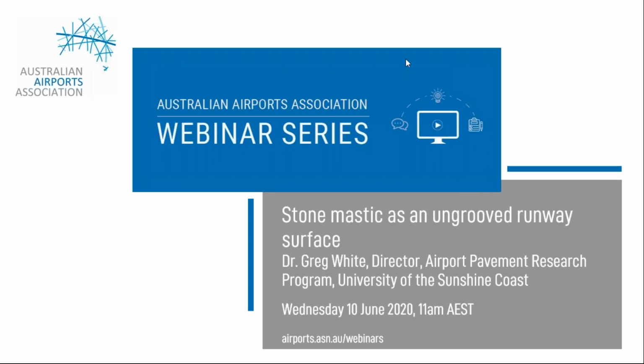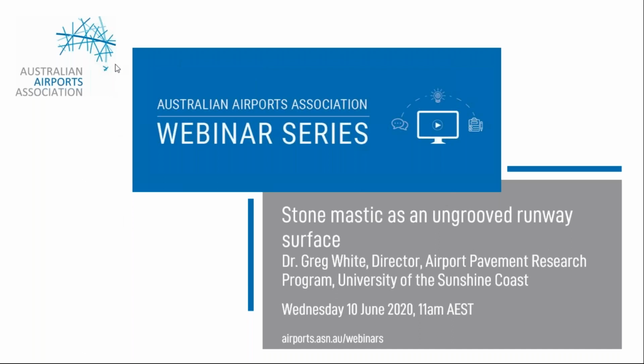Well, actually 0.4 of a millimeter is quite a lot in terms of surface texture depth. There's a big difference between 1 and 1.4, and there's a really big difference between 1.4 and 1.8 in terms of how things look. You think about how much grooving changes the look of your runway surface, and it's effectively adding about 0.6 to 0.8 of a millimeter. So those numbers, even though they're quite close together, they're still a long way apart in terms of practical outcomes.